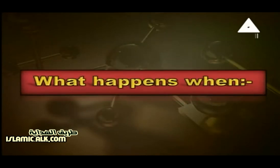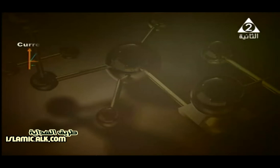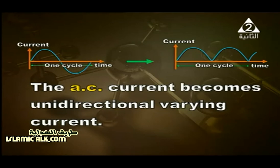And now we've got another type of questions. What happens when the two metallic rings in an AC dynamo are replaced with a split cylinder commutator? The two metallic rings are replaced with a commutator. The current changes from AC into unidirectional pulsating current. So the AC current becomes unidirectional varying current.